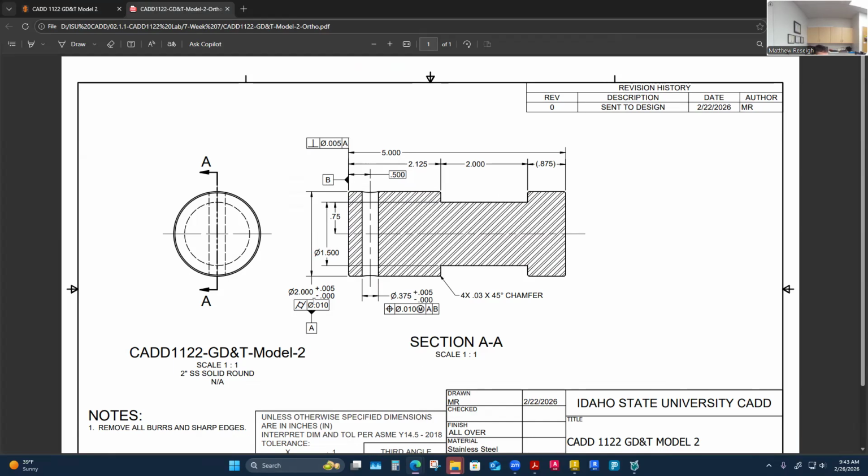Datum here, so this is one that we haven't applied yet to a drawing. If I recognize what this is saying, this datum is right in line with the dimension. So the dimension on this 2 inch, I'm applying my GD&T symbol right to that. That means this is specifying an axis type datum here. So datum A is the axis through the part this way. If the GD&T were slightly off here, then it wouldn't apply to the axis necessarily. So those small changes in where I put my feature control frame differentiate between surfaces and axis or planes.